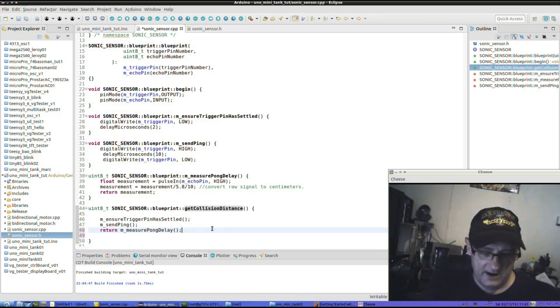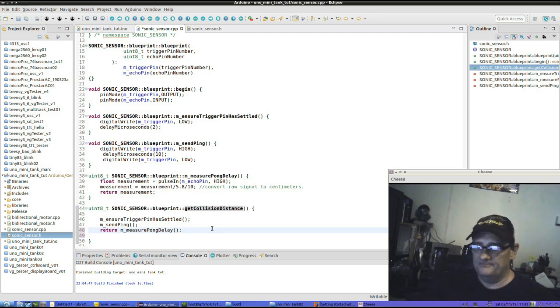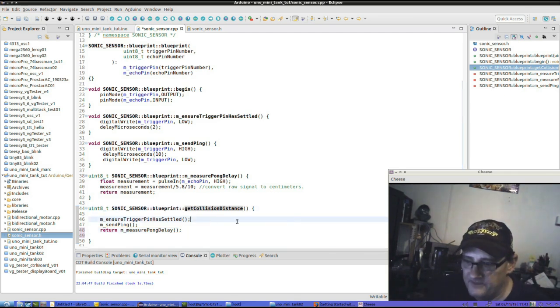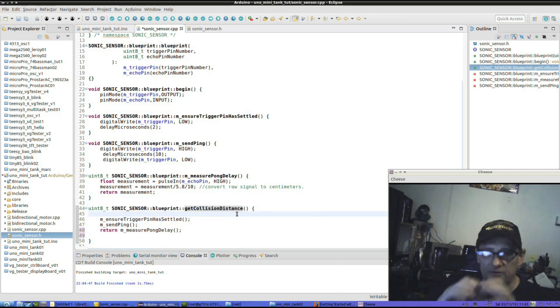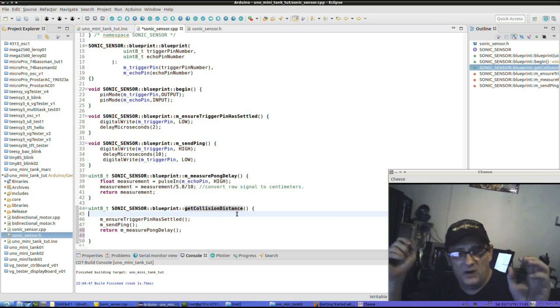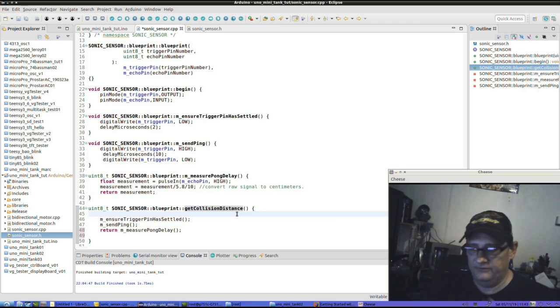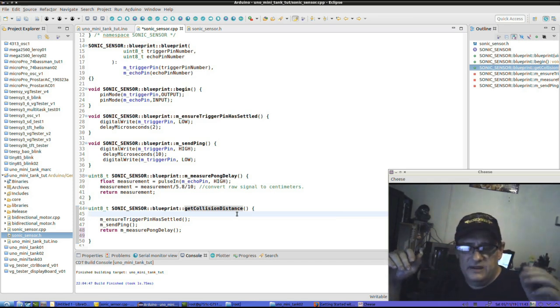And so what I found by playing with that, I've got another robot over here, I've been playing with that sensor a lot. And what I found is if you take the measurement twice, two times in a row, and you get the same value back two times in a row, you can pretty much assure yourself it's pretty consistent, so that's probably fairly accurate. But if you take a measurement twice and you get back two different numbers, most of the time it's some erroneous static data or static signal that's just unstable. So you can't really rely on it.